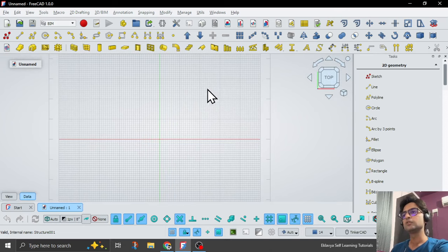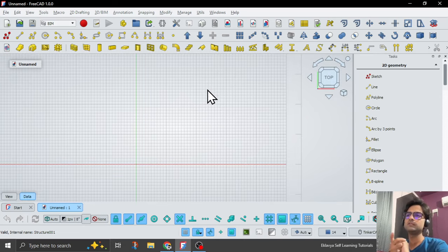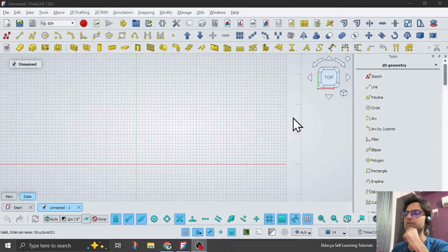Quickly, how we want to model this container house is that we will have a slab which will control the length and width of your house. Then we'll have height, and then some curtain walls for which we will also add parametric properties, so that you can control their nature and sizes directly from your VarSet.